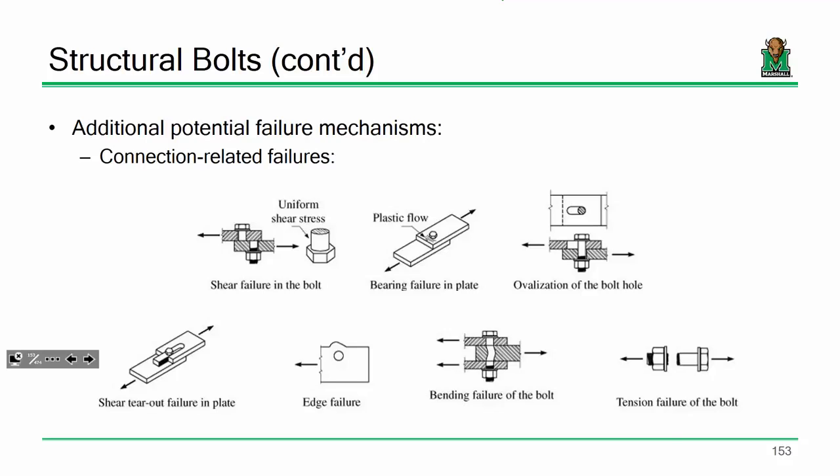Well, we really don't want that to happen either, because that could potentially lead to tear out. Actually, that little bit of plate right there, just ripping it out. It's almost like a mini block shear, right? Just taking that little sliver of plate and just ripping it out. Imagine that happen across the entire connection. That's obviously something we wouldn't want to have happen.